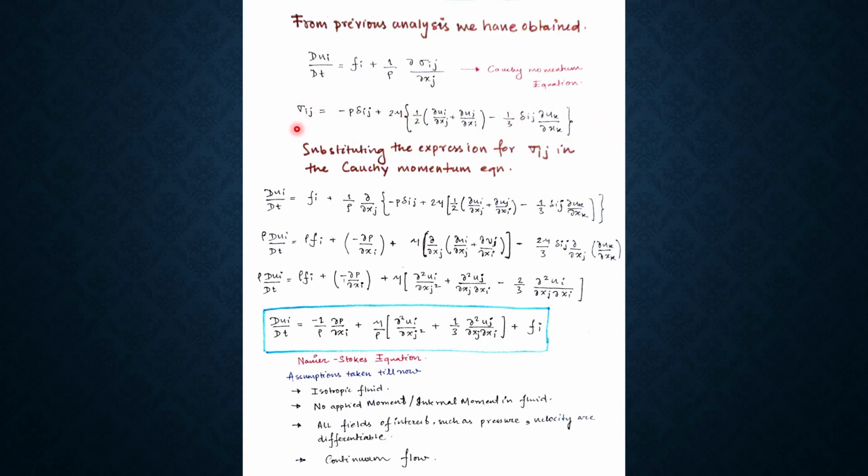And in the previous step, I just proved this expression. Now when I substitute this sigma_ij in this equation, it becomes like this. Now I take this ∂/∂x_j of each term by term. For the first term, this is the p term, we have a Kronecker delta_ij. Then the only point when it survives, that is, it doesn't go to 0, is when i equals j. So we do that, and it becomes minus ∂p/∂x_i, the partial derivative of p with respect to the x_i component.